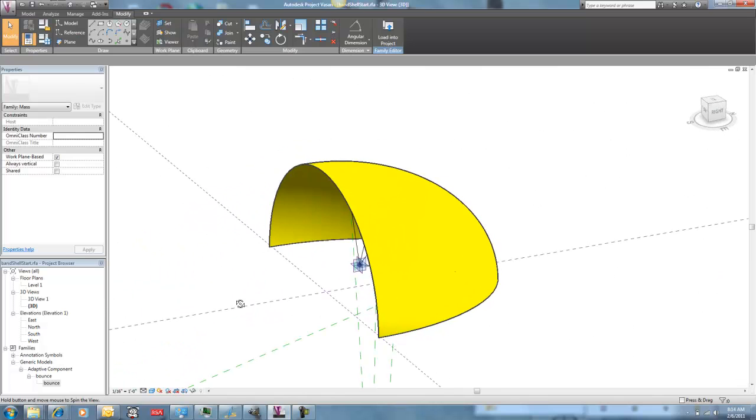And then I'm going to take this guy and I'm going to set it to just another angular value, ang2. And it's also going to be an instance parameter because it's going to get driven by this angle 1. So up here, if I go and I set angle 2 to be equal to angle 1, okay. Now I've got this thing that's basically mirroring this angle. And if I change this guy, I can see how it adjusts, and you can see that these guys are both reading out at the same angle. Right?